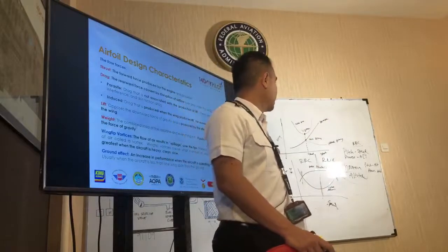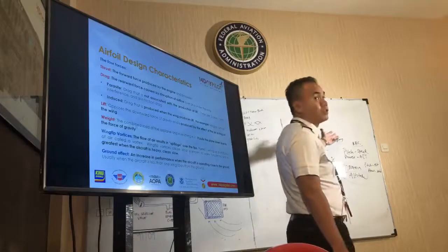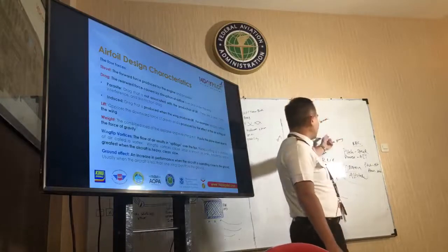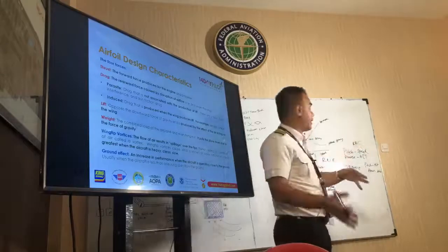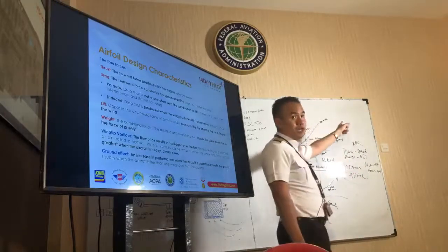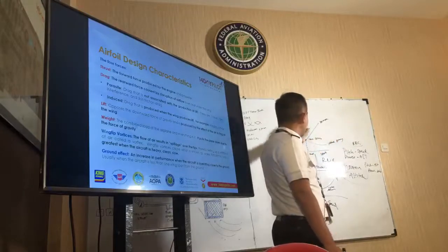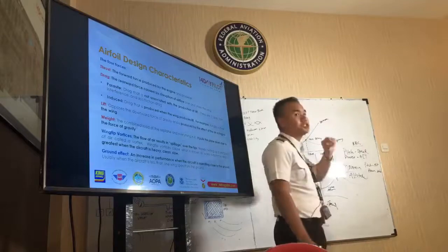That's about the drag. So, the induced drag: how does the induced drag work? The induced drag works by the production of lift. I will show you why after this. And then we have parasite drag, which increases with the speed, right? Then in the middle, the intersection, we call that the minimum drag, which gives you that speed.